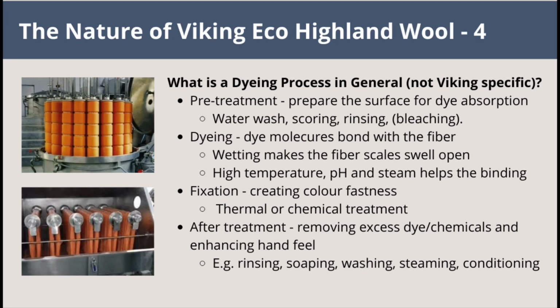So let's look at the first poster. And you can see the first step is the pre-treatment of the yarn. You have the wool or the fleece, and you need to remove dirt and waxes and oils and so on. So you apply a water wash and a rinsing and sometimes a bleaching. But I would say there's no bleaching here, but as I said, they informed that colorway 200, the white one, that is bleached.